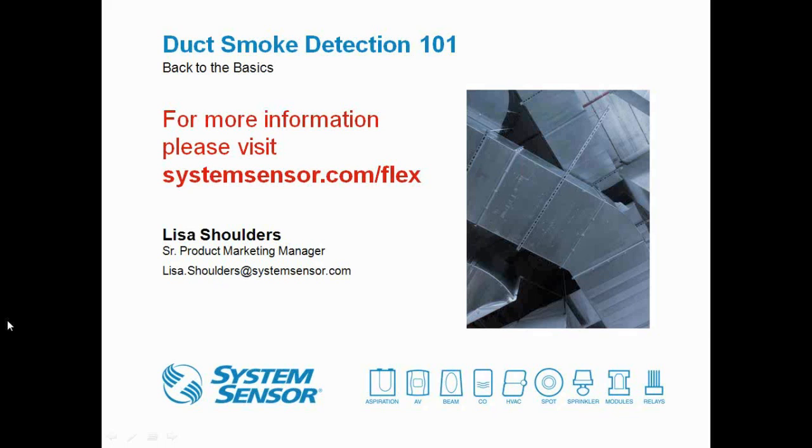Can the option of using two sensors tied back to one power board be done with your intelligent duct detectors? Again, that's a question that we get asked a lot, and unfortunately the answer to that question is no. That feature is only available on our 4-wire conventional models, but if you did want to do it, you could. Obviously, you can't use the actual intelligent product, but you could tie monitor modules to the conventional product and still achieve the same goal. Okay.